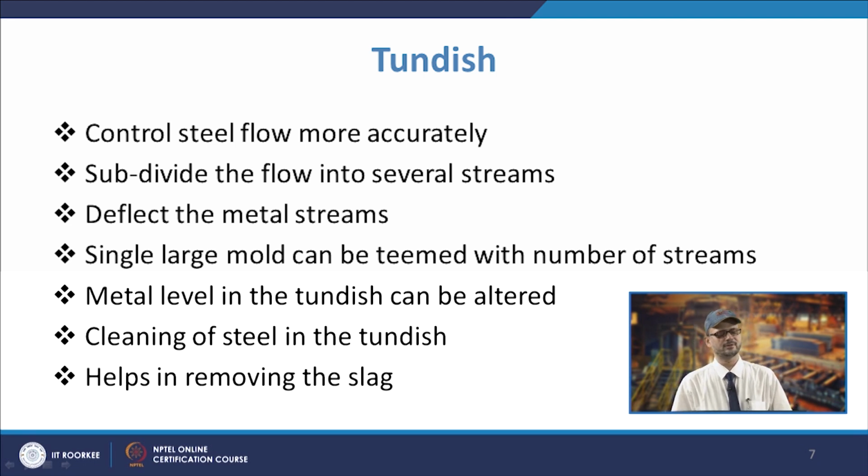Then you also have the possibility of cleaning of steel in the tundish. In the past it has been seen that the cleaning operation is also done in the tundish. Even now we think of having the tundish act in such a manner that if there are any inclusions, they must float.